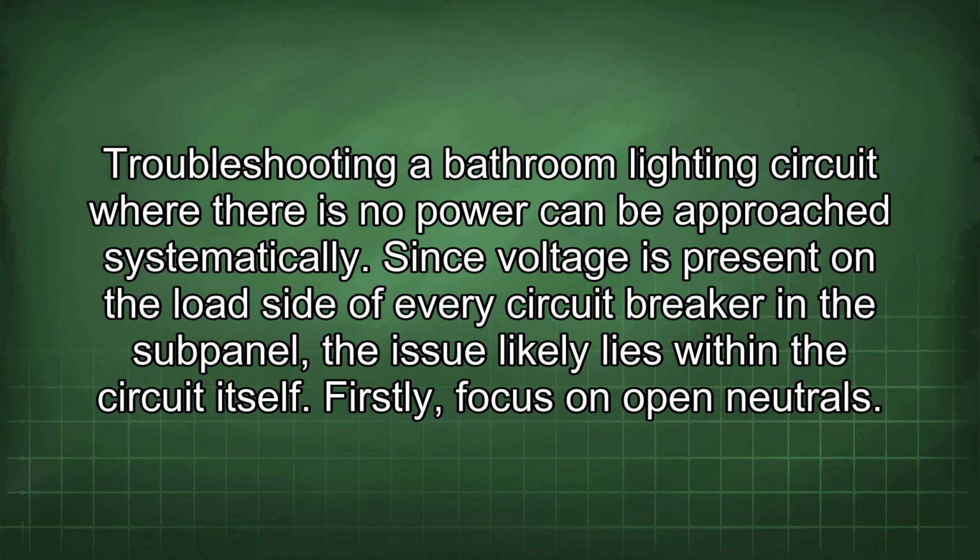Troubleshooting a bathroom lighting circuit where there is no power can be approached systematically. Since voltage is present on the load side of every circuit breaker in the subpanel, the issue likely lies within the circuit itself. Firstly, focus on open neutrals.